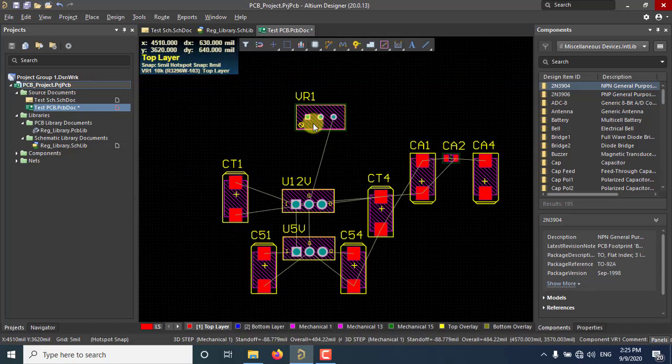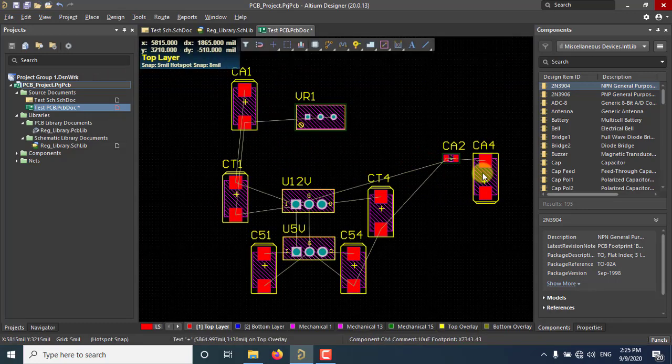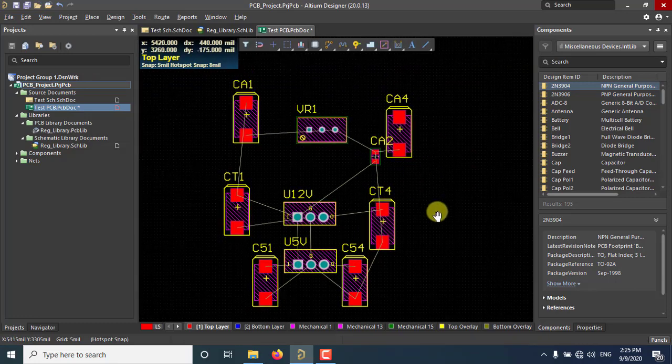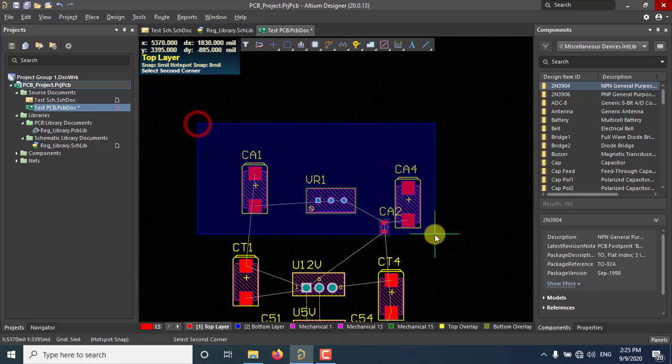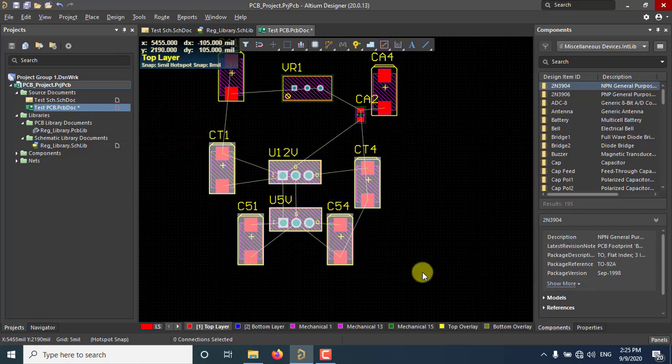Alright, so what I'm trying to say here is that you can just put them the way the schematic is, like you can classify these components into the adjustable regulator. Like I'm placing the adjustable regulator on the top, then I'm placing the fixed 5 and 12-volt regulators at the bottom.